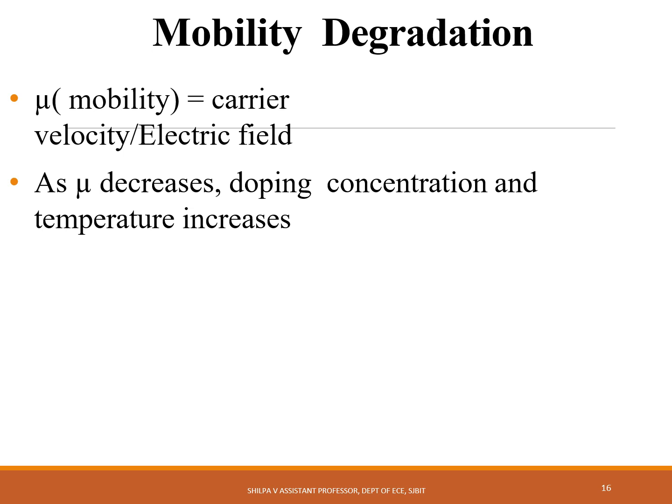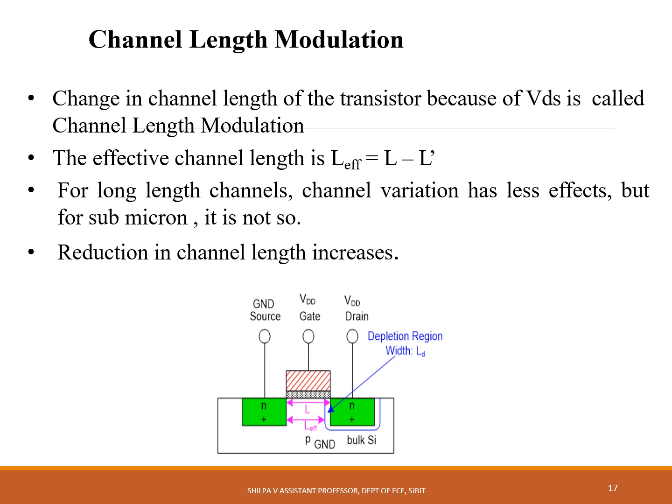At high voltage at the gate of the transistor, which attracts the carriers to the edge of the channel, collisions occur with the oxide interface that slow the carriers, and that is called mobility degradation. The carriers approach a maximum velocity, V saturation, when high fields are applied, and this phenomenon is called velocity saturation.